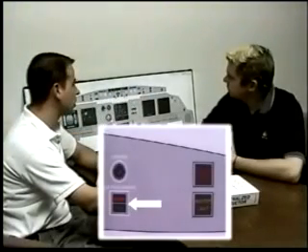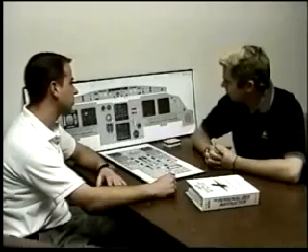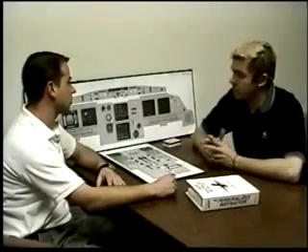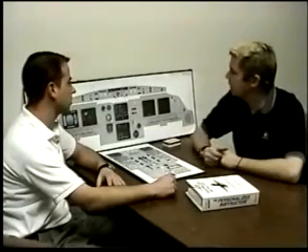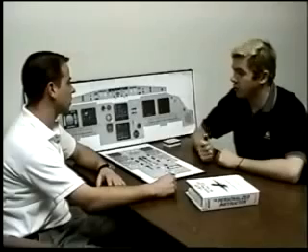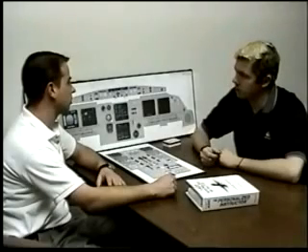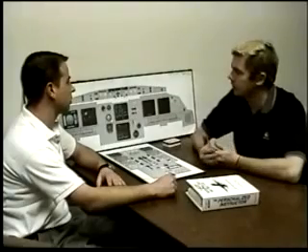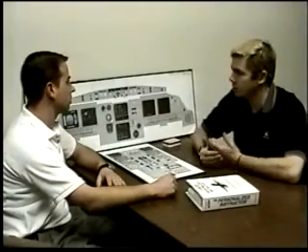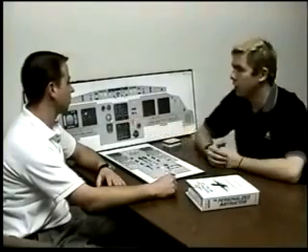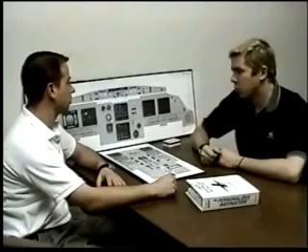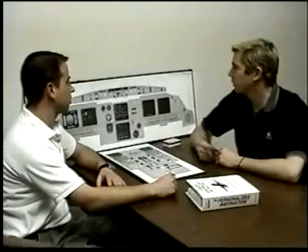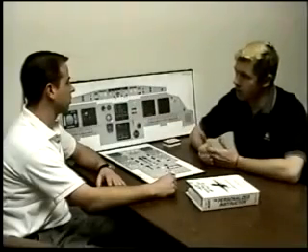Explain to me side stick priority and the indications. Okay, first of all, we've got the button on the side stick. If we just click it one time and the autopilot's engaged, it'll disconnect the autopilot. Problem with just clicking it one time is it'll give us the master caution, an aural warning, and we'll get an ECAM. If we click it twice, though, it will give us the master caution sound, but the ECAM won't come up and remain up there.